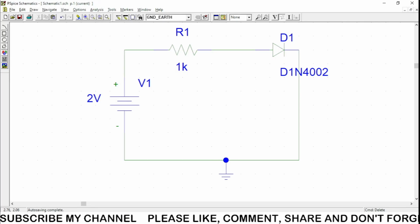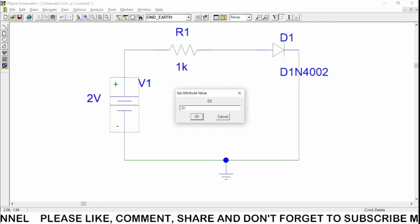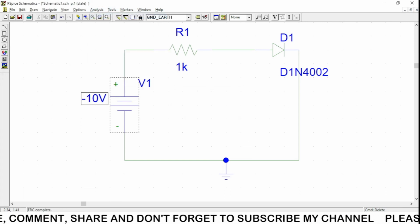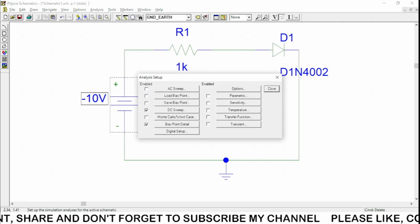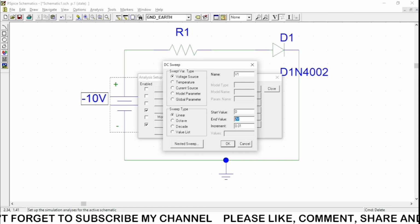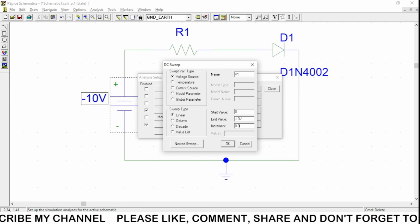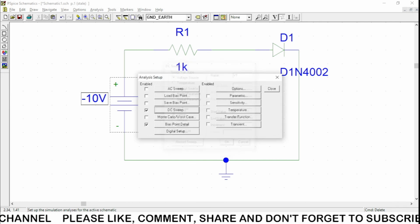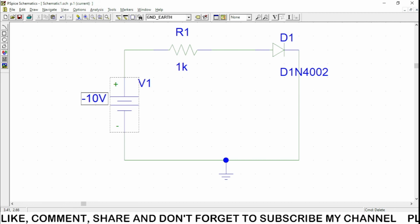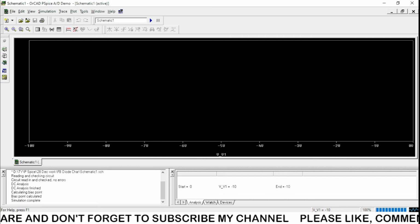So to see the reverse bias characteristic of a diode, just change the polarity of the supply to minus 10 volts, suppose, and then we are going to have analysis, electrical rule check analysis. In that setup we have to go to DC sweep, and we should start with the 0 and it will end at minus 10 volt with the increment of 0.1. I'm saying okay, close, analysis, and then simulate. We are going to see the graph. Okay, so in that the voltage is from 0 towards the minus 10.